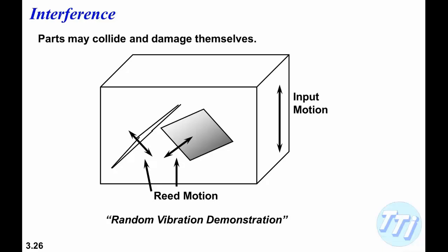So, the fundamental question here is, when we're doing structural dynamic testing, do we want to use sine or do we want to use random? In this particular case, we obviously want to use random. However, there are some other cases where we very definitely want to use sine. It depends on what kind of failure we're actually looking for.